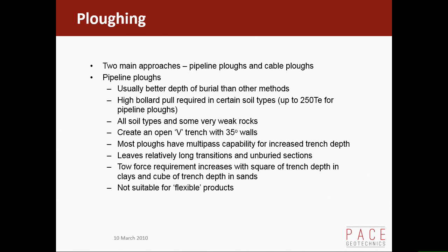Just talking about pipeline ploughs, technically it's the best burial method, I would say. It usually is. In terms of trench profile, you get a very good trench profile, and a well-defined trench, and they can trench pretty well all materials. A big problem is this thing, high bollard pull. You need 250 tons realistically, and ideally a bit more than that. And there's not many ships like that, and they burn a lot of fuel, so they're difficult to get.